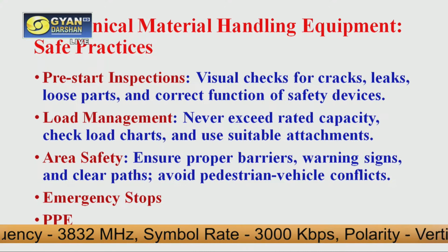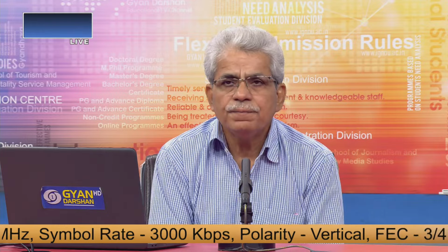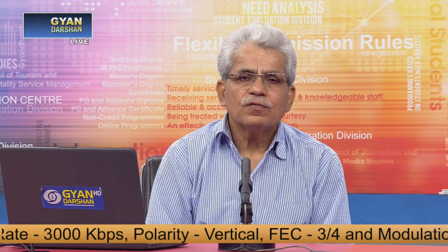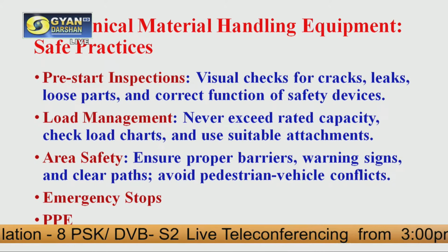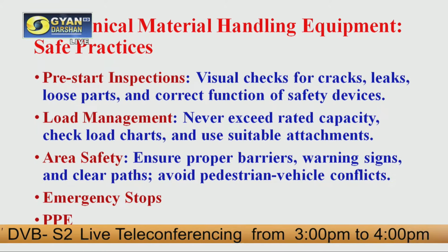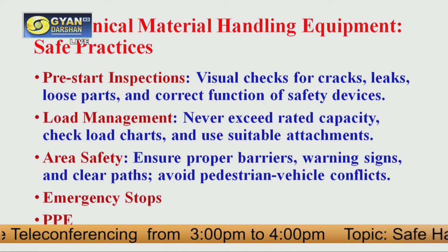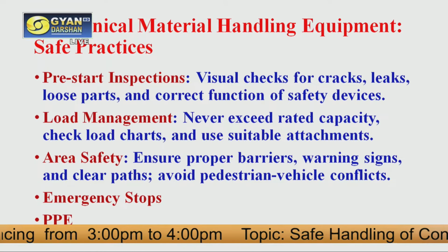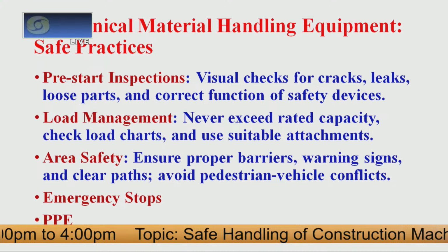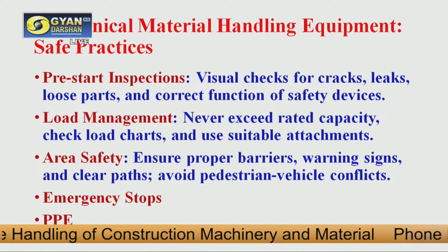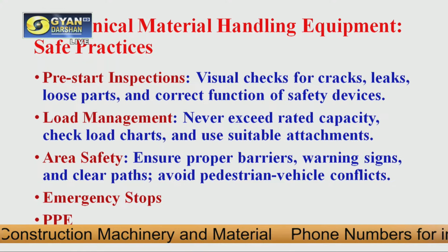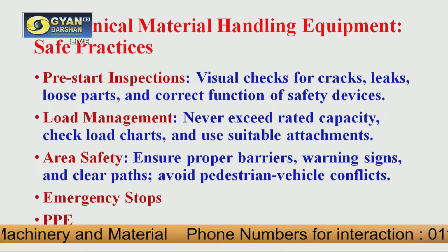What you should check there is whether there is any torn part, broken thing, any crack in any part, or some missing part, or some wear and tear in some part which is clearly visible basically. So if something is there, then don't use that equipment or machinery till it is repaired.